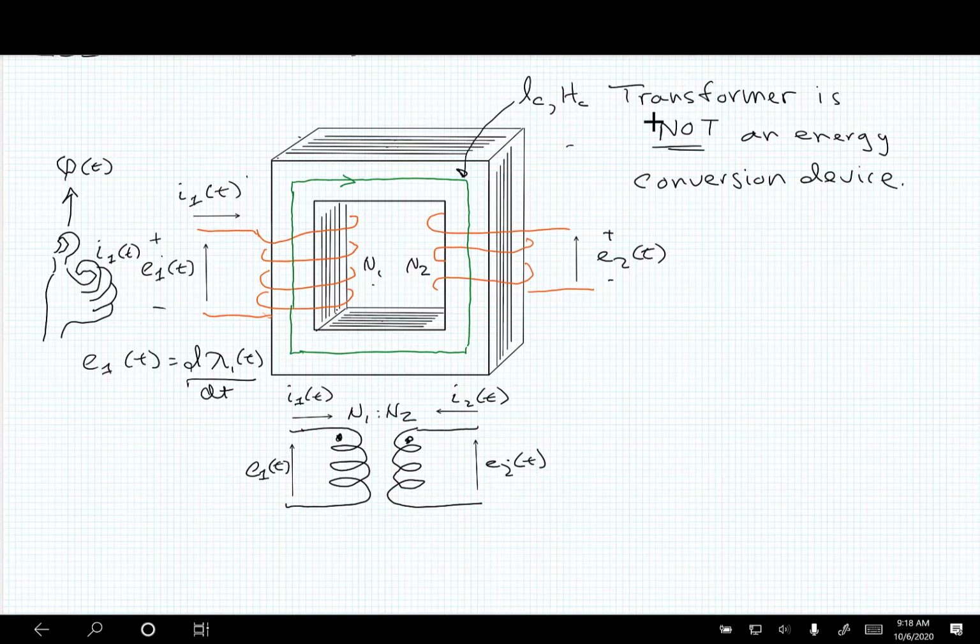There's a flux density of the core, remember, BC is mu H in the core, and the flux is flowing through the whole structure here, but we will just represent it as the flux line in the middle that's right along with the H.